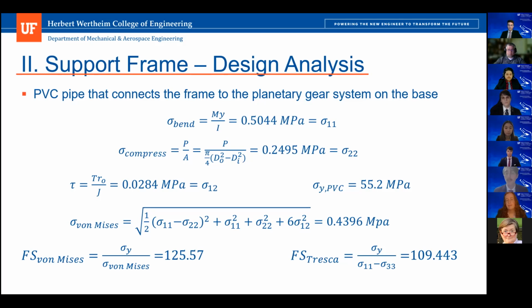The drag force on each reflector, assuming the worst case scenario of the reflectors being angled at 90 degrees and perpendicular to the wind direction, is 252 newtons for a total wind load of 1,008 newtons, while the length of the angle stock base is 0.762 meters. This results in a maximum moment on the pipe of 768.096 Newton meters.